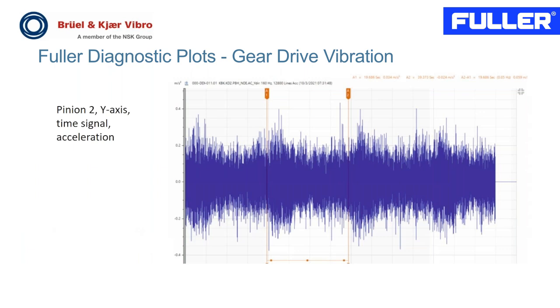So ovality and the crank, as we mentioned before, these are kiln shell potential failure modes. And I'm going to talk a little bit about the gear drivetrain. The gear drivetrain, as I mentioned before, is the girth gear, the pinion, and then the motor in the gearbox driving the pinion.